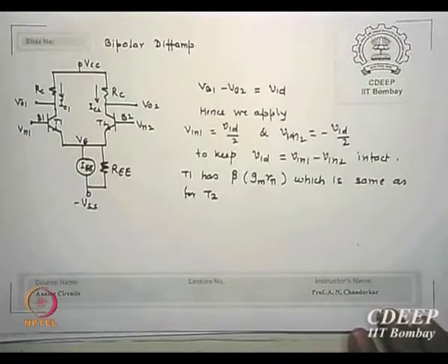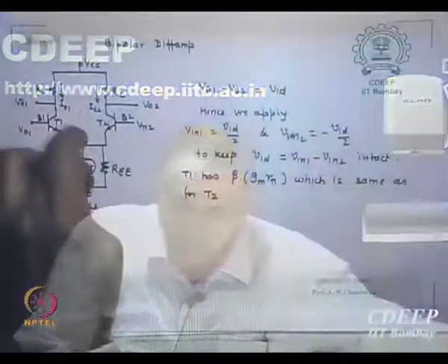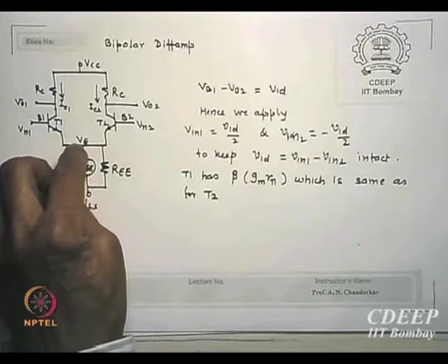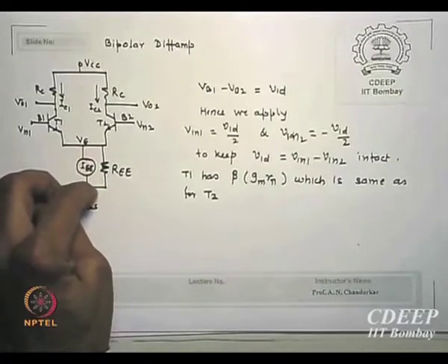Otherwise RS plus will keep coming again and again, and you would have to keep carrying 10 ohm and 1 megaohm repeatedly. That is why I am saying that in my circuit I don't use it, but you will see in books that they use this term because they are actually solving the full circuit, so they will show you the RS part, the small resistance I showed you between substrate and emitter. So the circuit will have this resistance here plus this resistance here. So the emitter will see a small resistance due to the emitter substrate, this plus RE.